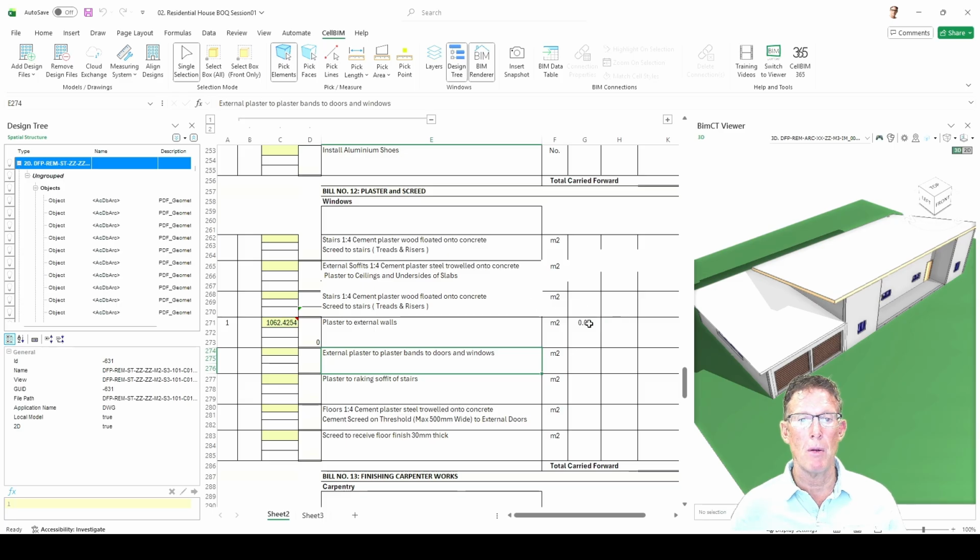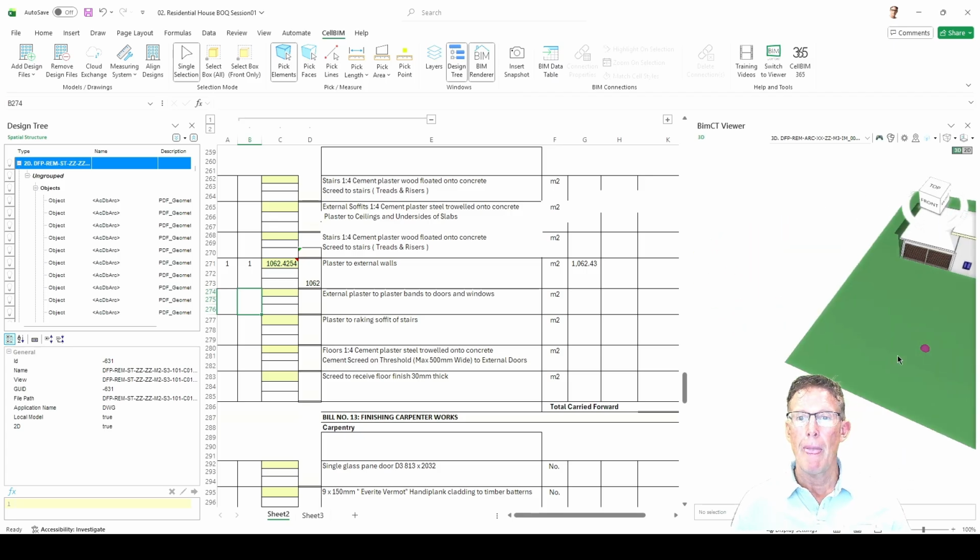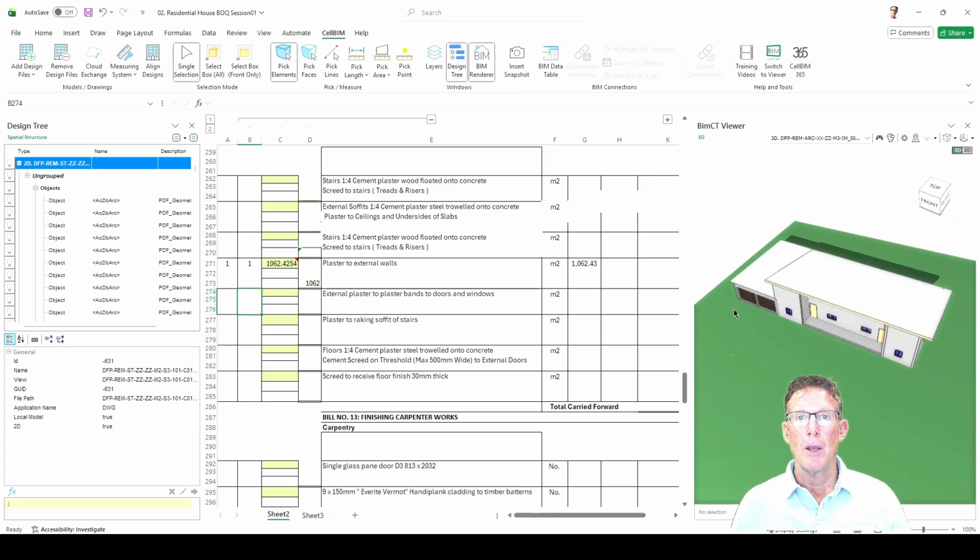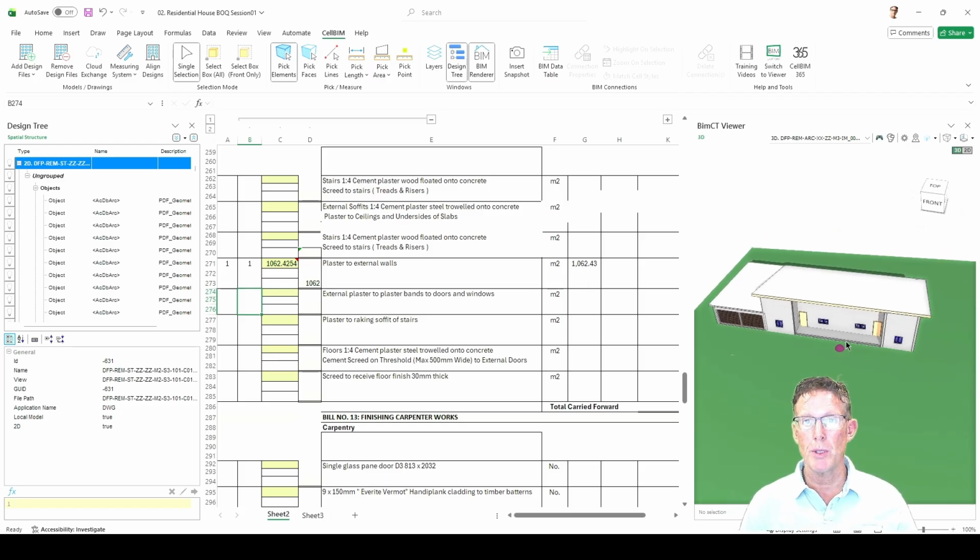Again, it's not appearing in the quantities because I have to put a 1, because we're only measuring one house. If there were 2 houses with the exact same quantity and we were building a development, I would select 2 and the quantity will double. All right, typical quantity dim sheet. So for this case, let's just move it back to 1. Right. So there was a brief summary on how we do quantity takeoff with 3D models.